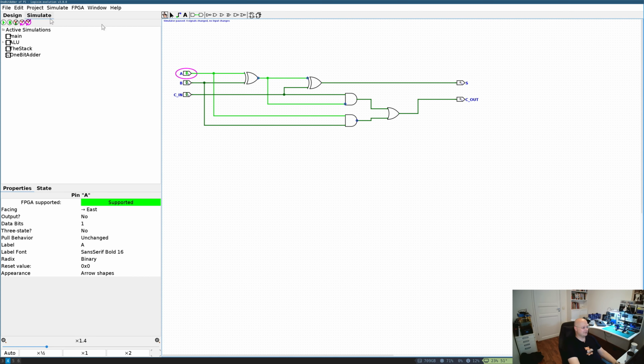Usually, people think of electronic circuits as super fast circuits. So you change the input and the output changes immediately. In fact, you change the input and the output of a gate changes with some delay. We call it propagation delay. And what's even worse, those delays are combined. So in my case, I have 3 gates between input A and output Cout.